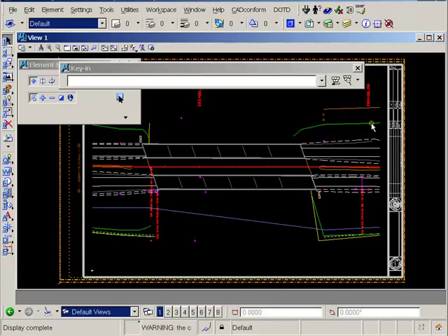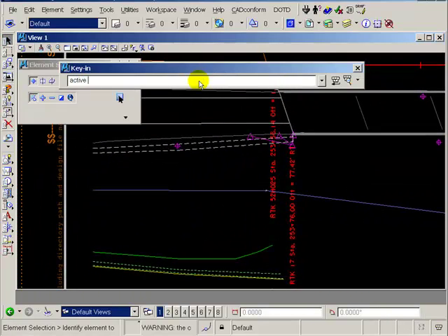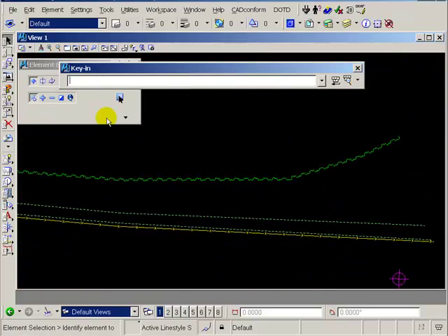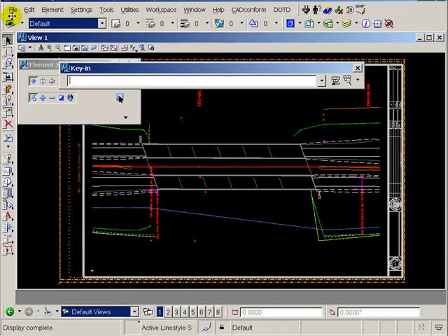Now I need to set the global line style scale. Using the MicroStation key-in browser, I will key in the command active line style scale 30 to modify the global setting in the new site plan file, and refresh the current view using the update view command and verify that the line styles display correctly. Finally, I need to save this change using the command File, Save Settings.